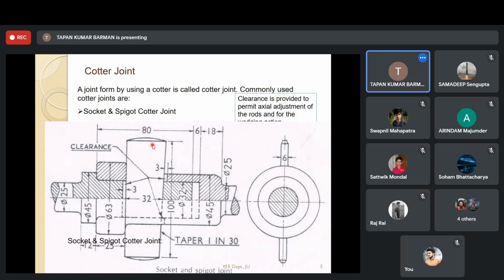Why is there no section line? From the concept of section, you know, when we cut an object and there is material, then we should put the section or hatch lines. Am I right? Yes, sir. So when I am cutting a component, there should be hatch lines.